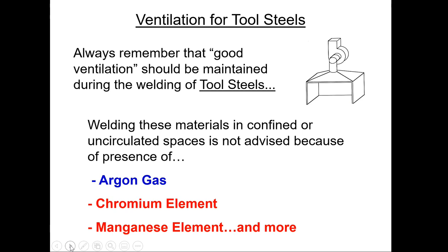Now, chrome and manganese are something you don't want to be breathing, and there's always fume. Where there's welding, there's fume. There's enough heat at 11,000 degrees, and that's what the plasma is coming off the end of your TIG torch. And there's enough heat in there to actually get everything to the point of almost boil. So there's fume that gets released from the process.